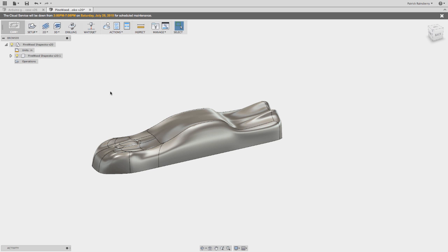Okay, the first thing that you need to do in CAM is to create a setup. A setup is like a folder basically that will contain a number of operations, typically for like say one side of machining, or what I really like with the X-Carve and Shapeoko is to do one setup for each tool I'm going to use. That way I can post out all the operations for one tool, run that, do the tool change, run a new set of G-codes.